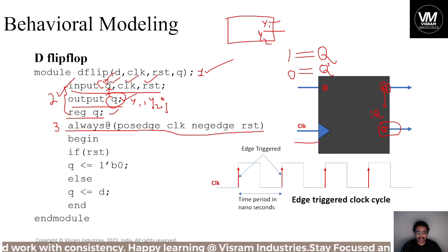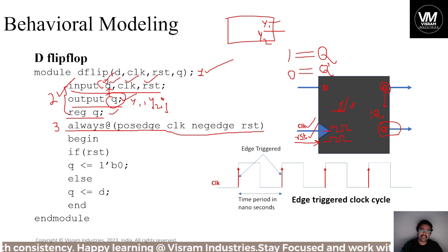So here we can also give another circuit. I mean, we need to reset the block, right? Whenever the data is stuck or whenever the data is in delay, or if we want to erase whatever the static data ones or zeros we have, that to be erased temporarily. So for that we use reset pin as well. So clock reference will be taken, and reset pin also will be taken. And also reset, why do we need reset? Sometimes for the ease of simulation.